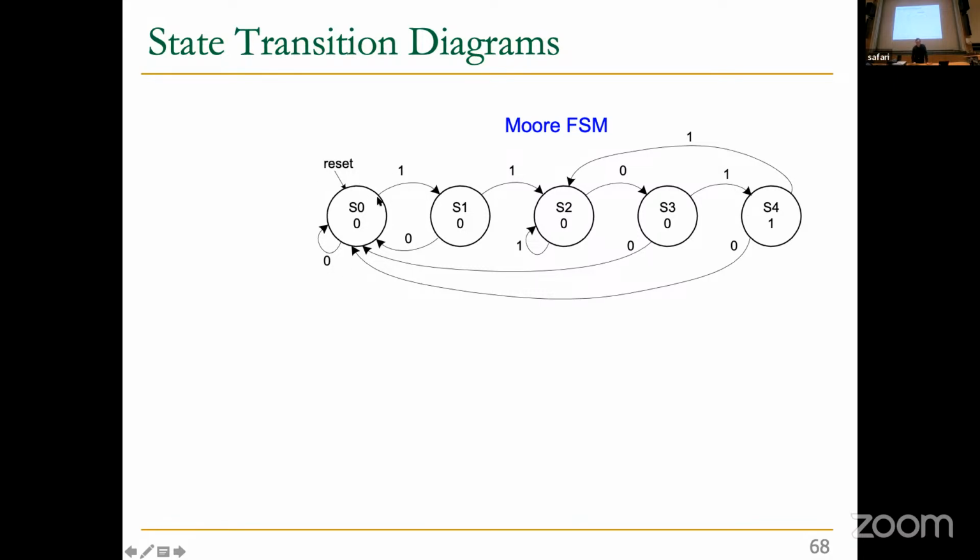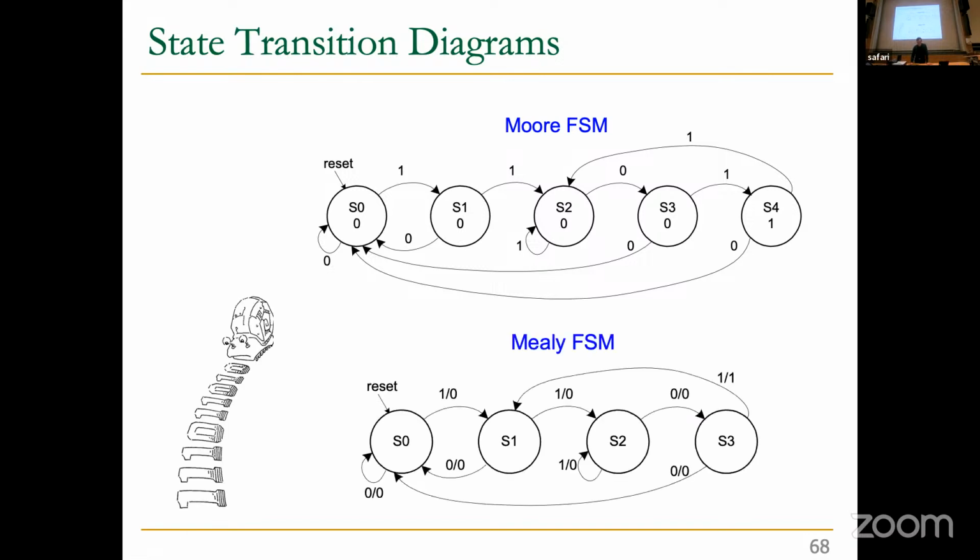And here we have 5 states. In the 5th state over here, you know that you have seen 1, 1, 0, 1 in sequence, and then this state directly corresponds to the output smile, and that's 1. Every other state, smile is 0, meaning the snail doesn't smile. And you can make sure that this works, and it works.